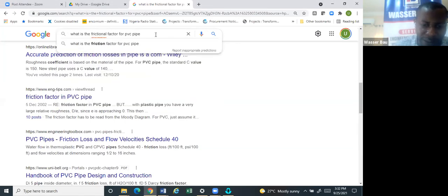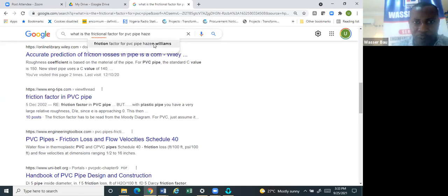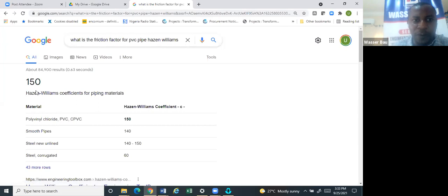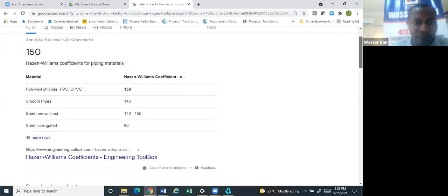So I can come here and say Hazen-Williams. Yeah, look at it. See that frictional factor for PVC pipe in Hazen-Williams, and it says 150. Smooth pipes 140. Can you see my screen? Steel new, 140 to 150. Steel corrugated 60. So if you remember our fluid mechanics, frictional factor can be Darcy-Weisbach, Hazen-Williams, or Chezy-Manning. So whichever one you are using, you put the appropriate value. So here it says 150.